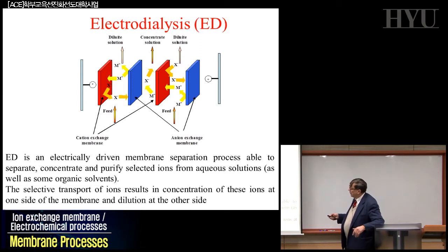Because in this way, if this membrane is cationic, the positive species will go across. Assume here transport number equal 1. All the electricity that is moving in the system is moving across these membranes. On the other side, chlorine ions will find anionic membranes and they will go across. So no problem. We are removing positive and negative ions using the selectivity of these two membranes.